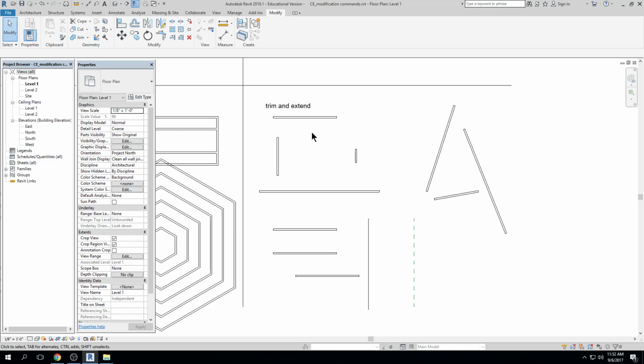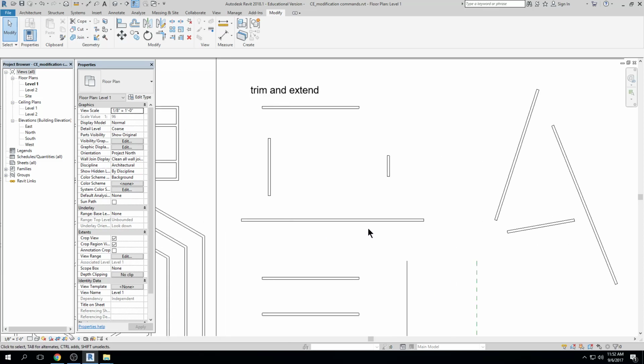In Revit, when you are creating squared off corners, which is generally what you're using trim and extend, or fillet in AutoCAD for, it's all one command. So in Revit, trim and extend, which creates a filleted squared corner, is one command, okay? So for example, if this was going to be an enclosed area, I would use trim to square off those corners. The keyboard shortcut is TR, and it is this command, this icon right here, TR.